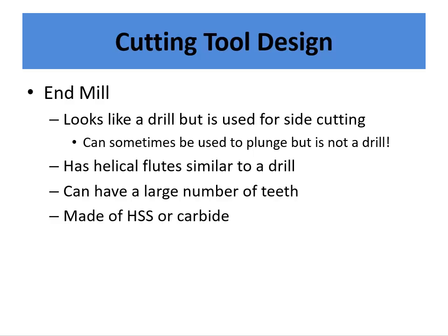Okay, and it has helical flutes similar to a drill, and they function similar to a drill where they can actually auger material out. But the edges of an end mill can cut as well, so you can side cut with that. And also, you can change the number of teeth that you have in an end mill. You could have 7, 8, 9 flutes, however many make sense, and there are advantages and disadvantages to doing that. And again, end mill design is probably even more expansive than drill design, although you could get a career literally doing either and designing them.